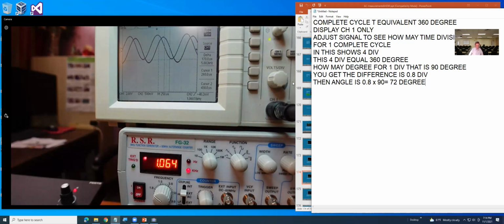So I hope we get through today. Later on, whenever you have to measure the voltage using the scope without ground, then you have to use channel 1 minus channel 2. That is one point.